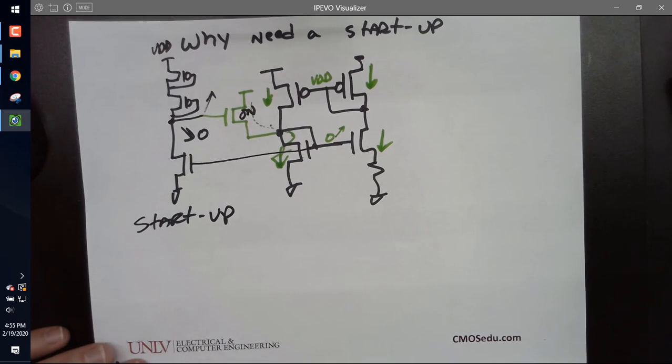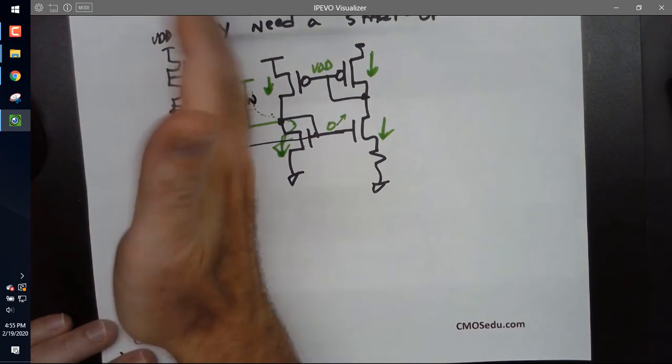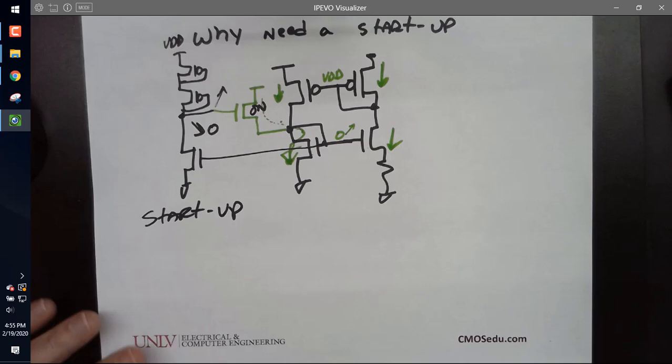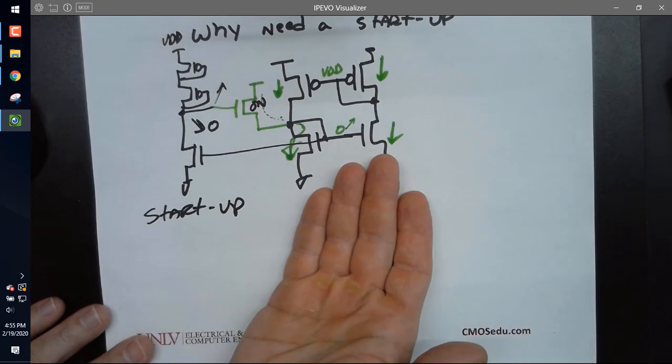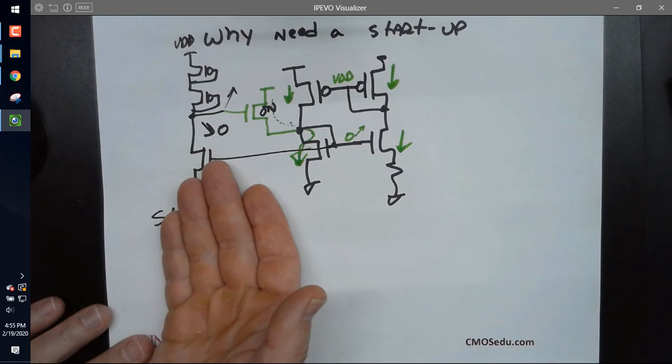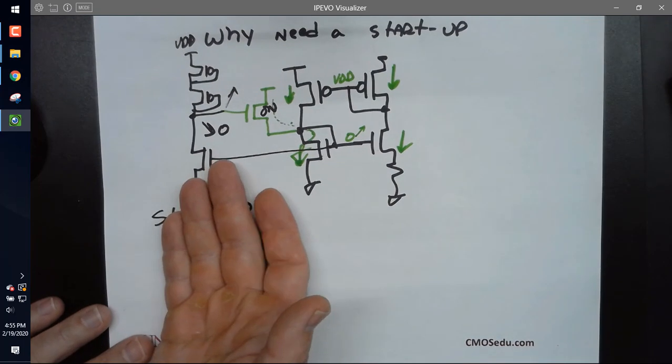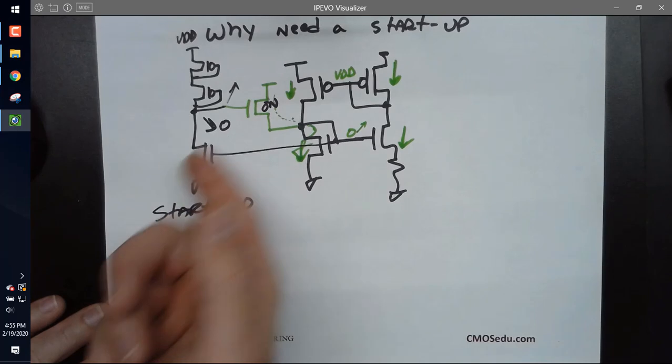Okay, so that leaks in, and you don't want the startup circuit leaking in. Like I said, you see right now, it doesn't do anything. Once it turns on, it doesn't do anything over here. But you don't pay attention to it, and then that's where all the problems are. You don't test it for the temperature and the threshold voltages and all that stuff.